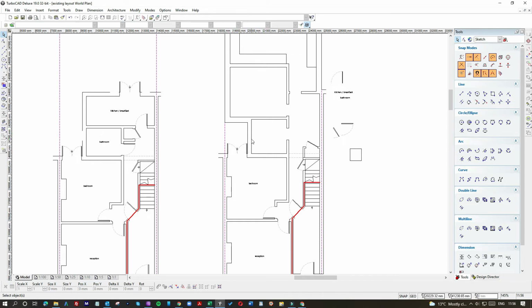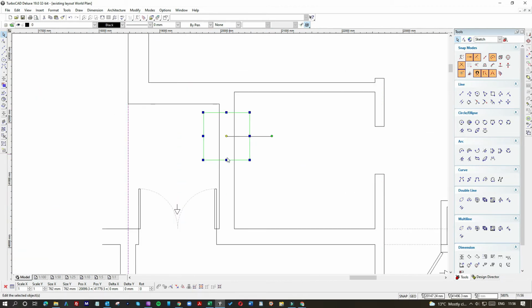So we're going to have a tub here, so the window would be on this side. Put in, doesn't have to be a huge window, but if we did something like a 650, let's go down there and change the size of this. 650, tab 650, tab. So now we put a window in on this side.